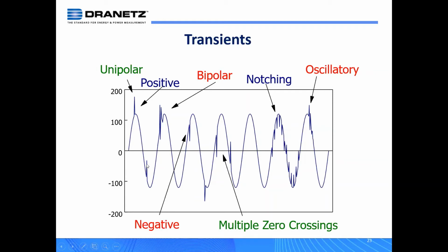Okay, so negative transients can be just as effective, or can affect your system just as much, but they're not going to blow something up. A positive transient may blow something up. A negative transient, for lack of a better term, may lock something up. You can see here is a positive transient, but also here's a negative transient that happens to be on the positive half of the waveform. And again, another positive transient here that's on the negative half of the waveform.